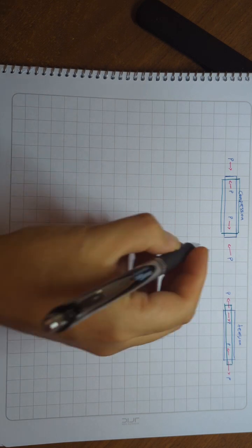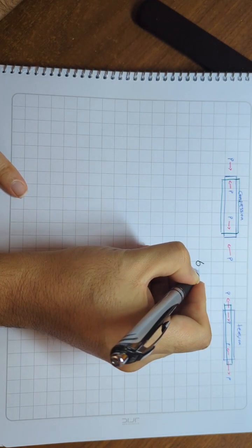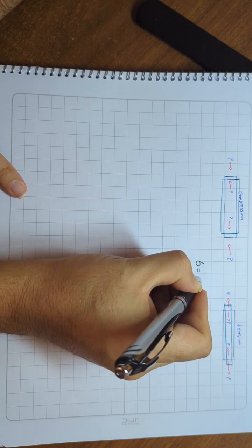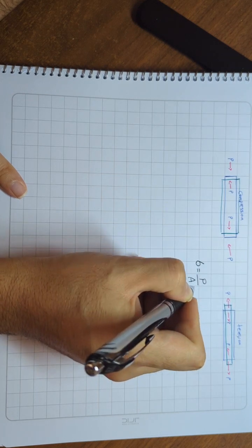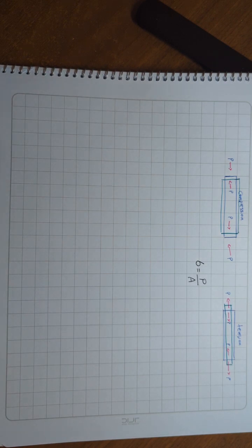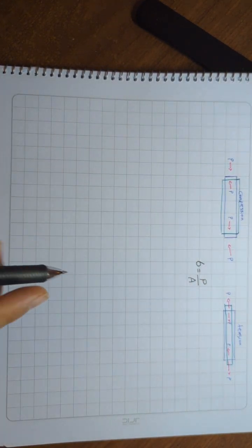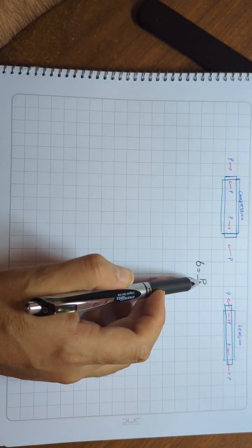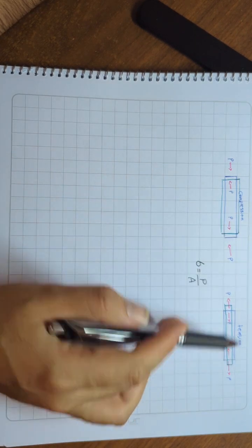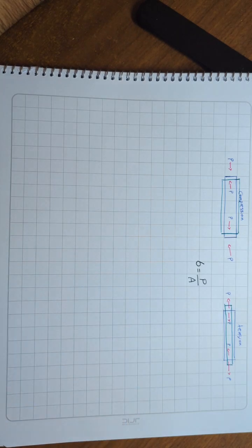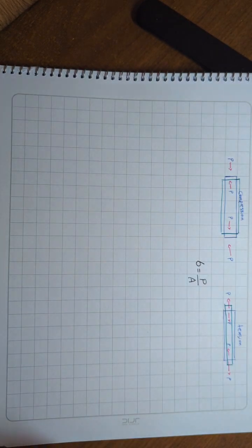Okay, so what are we doing here, and what are we looking for? We are looking for the stress, the amount of stress that we can put on each material, and this stress can be calculated by this formula. So sigma equals P over A. So what is sigma? Sigma is the stress that we put on the material, that the material is undergoing because of the forces. Okay, and what's the P? P is the external axial load, which is on each material that we are calculating. And what is A? A is the area of the cross section which the load is applied on.